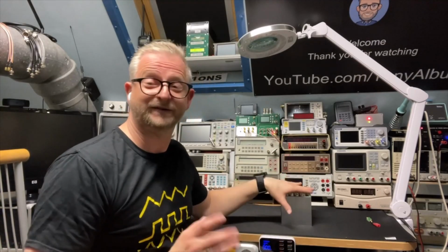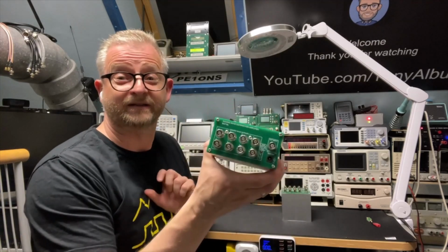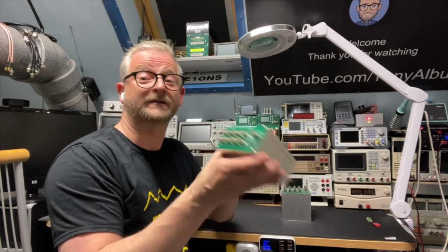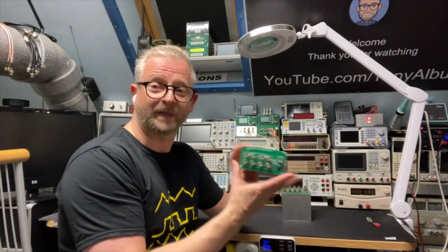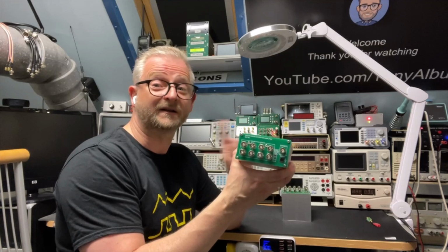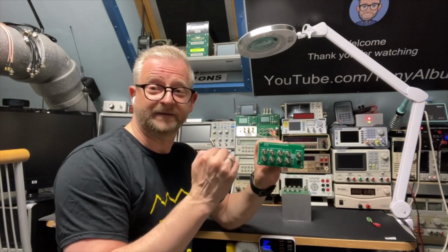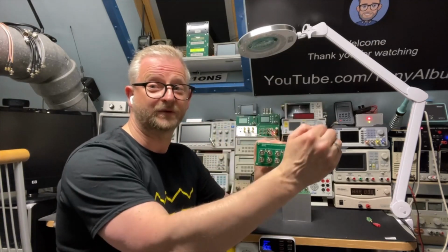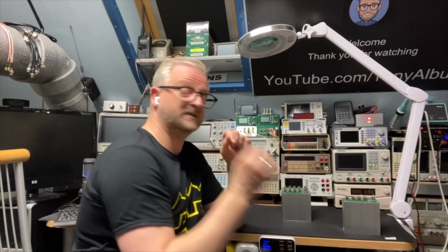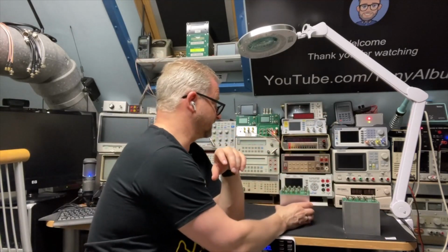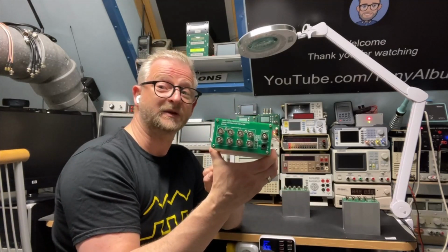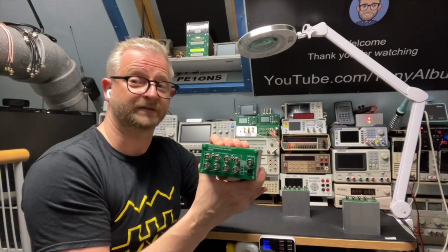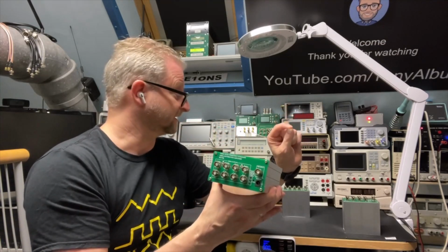So that was a little bit fast and a little bit messy, but a little roundup. The cheapest one is the square wave distribution amplifier or trigger signal distribution amplifier. And this is perfect if you need a frequency other than 10 megahertz, and you can do from 0 up to 200 megahertz. If you want a clean signal and you use it for external reference 10 megahertz only, then you use the 10 megahertz distribution amplifier, a little bit more expensive, but all your harmonics are filtered out. Very good.